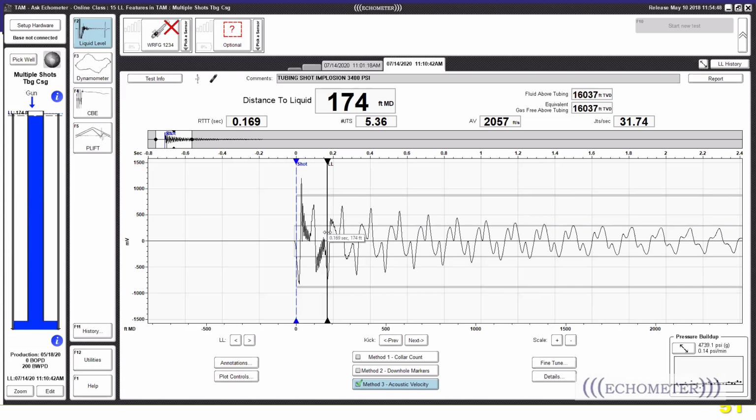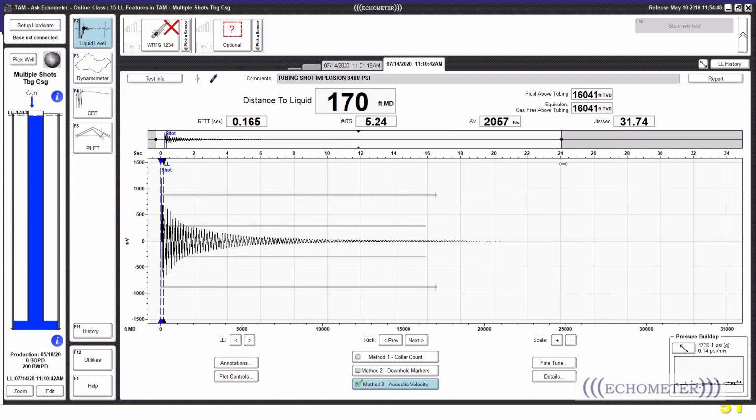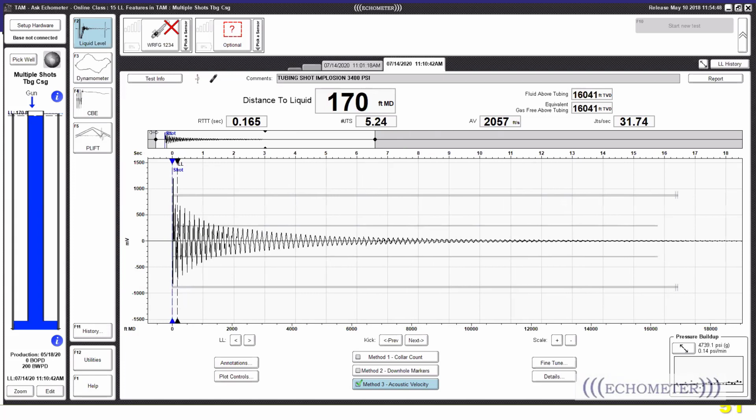Well, if that's a hole, is it possible that the liquid level may be here? Well, we have over 4,000, almost 5,000 psi. So there's no way that this well, with 5,000 psi, is a gas well that might have such a high liquid level. That would result in extremely high downhole pressure, which is not true. So we don't know where the liquid level is at.